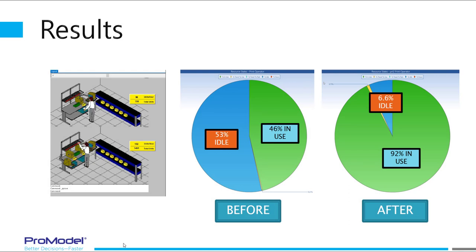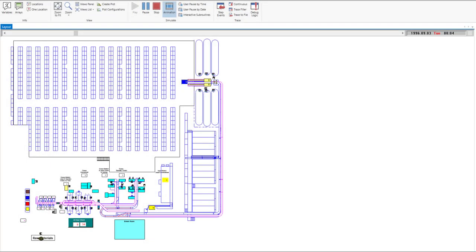The data clearly showed the two-printer option was best due to the increase in saved space, and the throughput and operator utilization far outweighed the cost of the additional equipment. The conveyor layout was redesigned in AutoCAD to allow space for the new printer stations and to determine the maximum number of stations that would be required during operation. The original CAD model was modified to reflect the new facility layout. After running a number of order scheduling scenarios, the design was refined to meet future projected demand requirements and would support up to 30% more demand if needed.